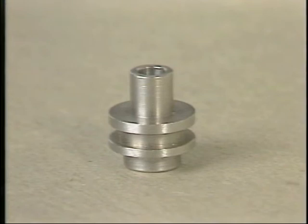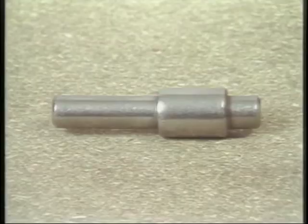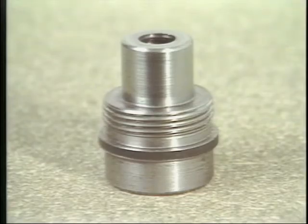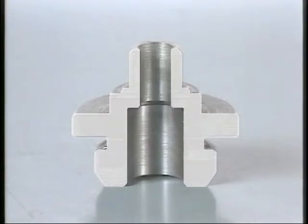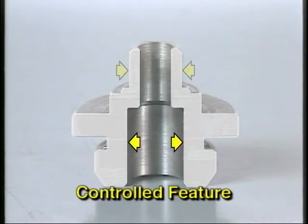True position is also used to control the position of one diameter in relation to another diameter when both have the same axis of rotation. This type of position control is commonly used with lathe, screw machine, and cold-headed parts. True position of these types of features controls their coaxiality. In this example, the outside diameter is the datum feature. This inside diameter is the feature being controlled.